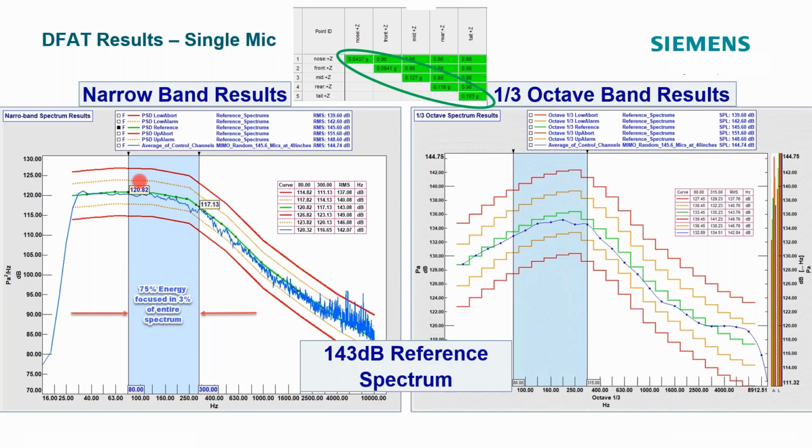If you analyze this, you can see this is for one particular control channel, and this is the PSD in acoustic units, pascals, and that's my PSD at one component of the spectral density matrix. And this is going to be the same spectrum for each of these control points.